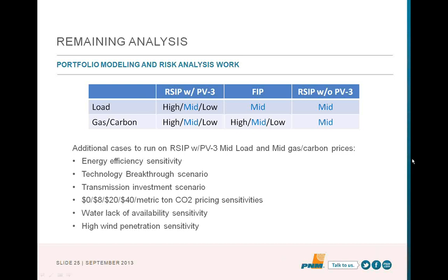And one of the reasons for my question earlier about the peaking plant rather than a combined cycle plant is that there have been combined cycle plants co-located with concentrated solar. So you use the thermal energy either from the combined cycle, from the waste heat off the turbine, or from the solar to run the steam turbine. Okay, so the comment is that we should broaden our definition of storage, not just electrical storage, but thermal storage, and look at some different combinations of where that can be combined with solar or other steam-using technologies as a benefit. So that's a good comment.